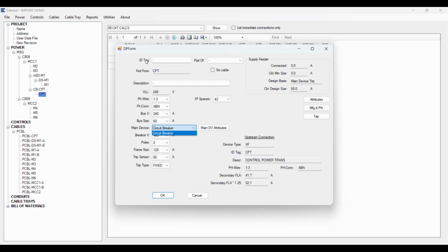And you'll notice on the distribution panel, otherwise referred to as a panel board, it only has a main device as a circuit breaker as possibilities. We do not need 42, and just to make it easy from a size standpoint, let's just give it 20. And we could call this LP1. Okay, this is now something I want you to see. Typically, this is a 52 as your max, and really, to be conservative, you would not really want to run a 60.